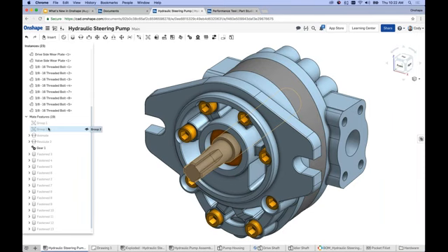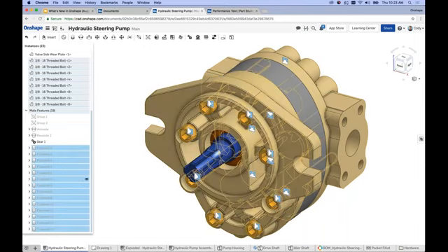Now, I know for many users out there that may not seem like a simple or a big thing, but I know for certain users out there, they're really going to like this one, because as you start to get more and more mates, and then especially as you start to add more and more mate connectors, right? That's another common use case. That's where this really becomes useful. Another example is, let's say that I like to group all the fastened mates together, and maybe that makes selecting them easy. Well, now I can drag them all together and shift select. If you're not familiar with it, you can shift select top and bottom, and it highlights everything in between. If you find yourself having to often suppress or unsuppress a group of mates at the same time, putting them together in the instance list makes them selectable in that way.